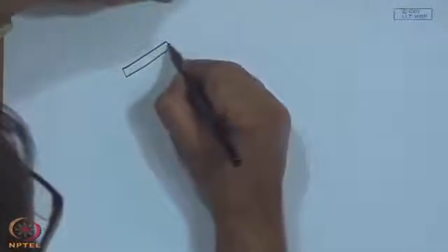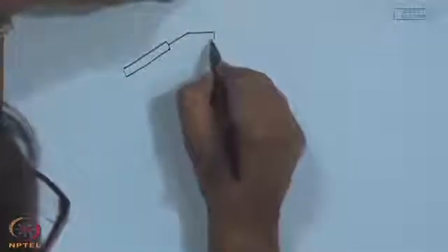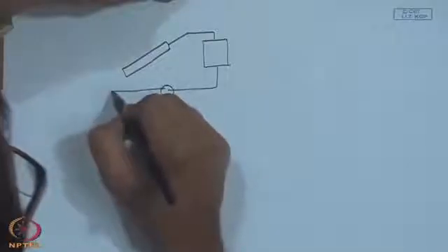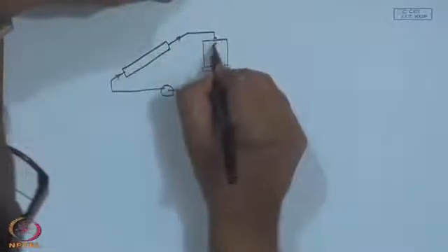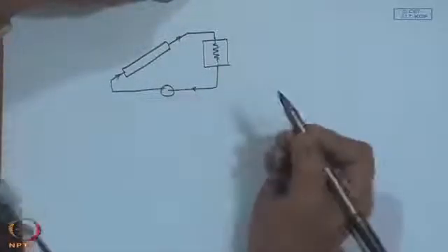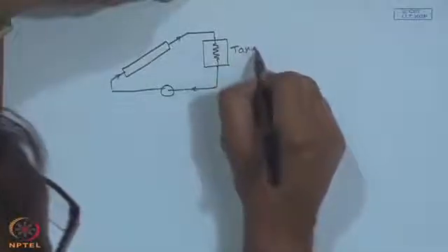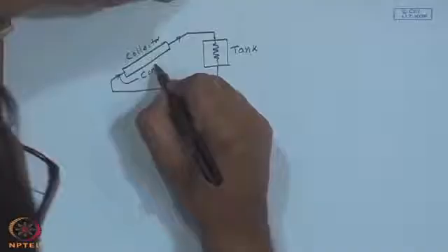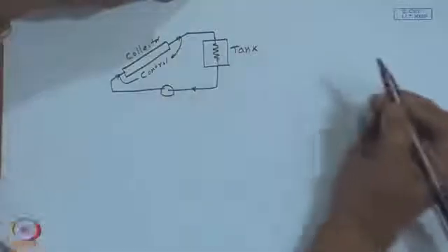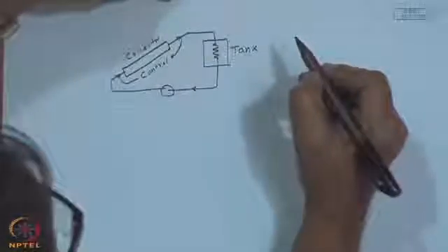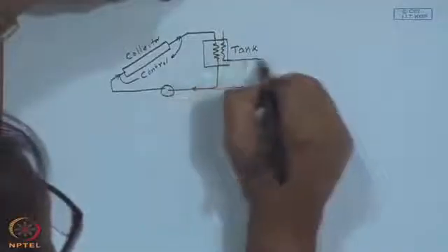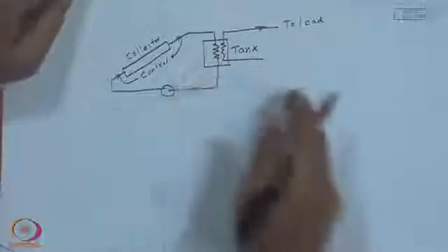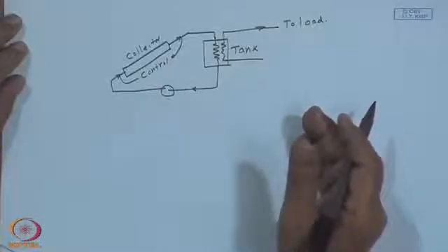Now, the other thing, when we talk about a single collector in a classroom type of situation, it may be going here to a tank, and it may be recirculated through a pump through this. We can say here is sort of a heat exchanger. Very simplified system diagram. This is the collector. Still, if I want, I may have a control which ensures that the exit temperature is higher than the inlet temperature. From here, I may take it to the load. So, if there is no heat exchanger, I can assume effectiveness to be unity, that will come to it in simulation later.